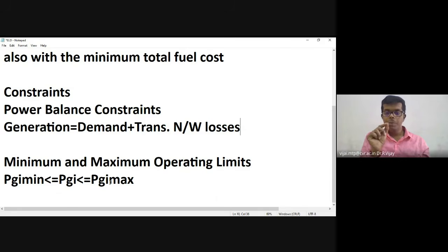If you note the speed of a hydel power generator, the poles might be 6 or 8, mostly 6, and the speed might be only 150 or 200 rpm, because the generator size is large, like 100 megawatt, and the turbine has to turn.